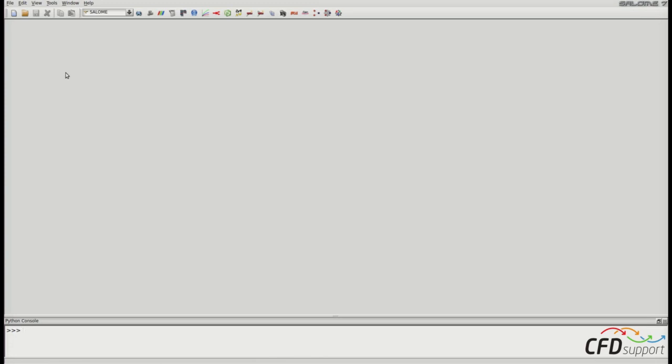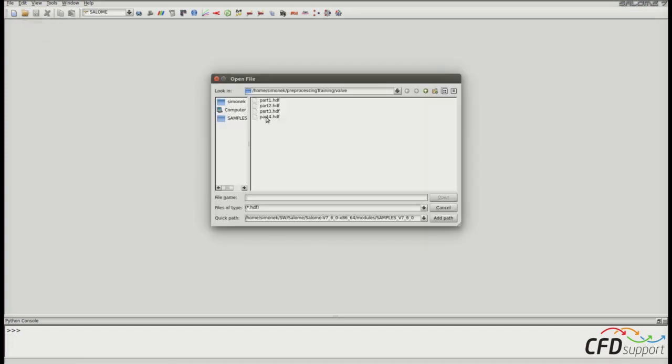You can continue working in the previous Salome session, or you can start a fresh session and load the part4.hdf file we have saved at the end of the previous video. I have started a new session, so I have to open the file from the 4th video. So I will click on Open, and I will open the part4.hdf.